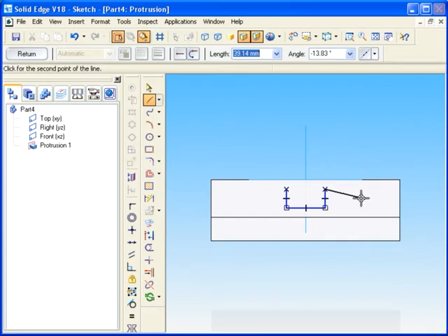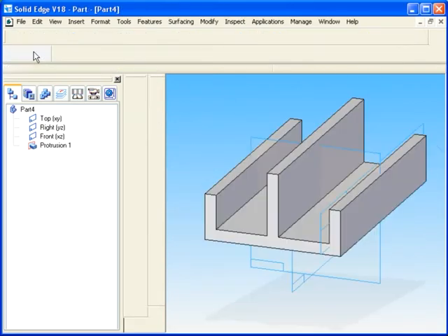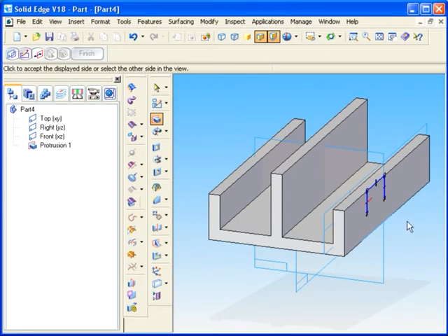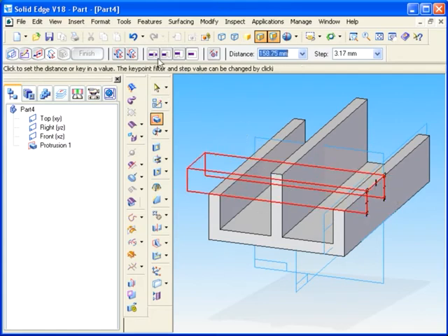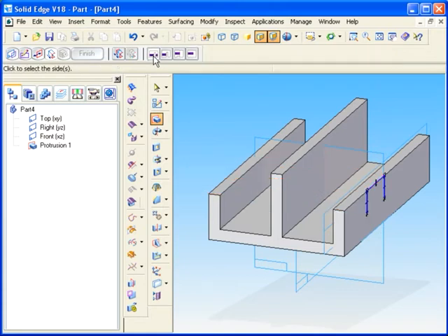When this option is activated, there is a small red arrow that displays. This is the direction of the feature, and it can be set to up, down, or both sides of the profile. The through next option extends the protrusion until it collides with the next face on the solid. You will need to set the direction of the protrusion, just like the through all option.